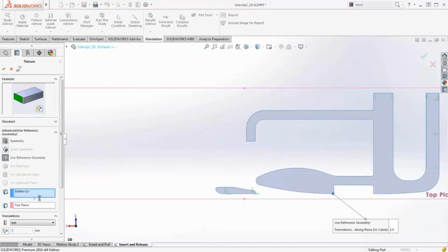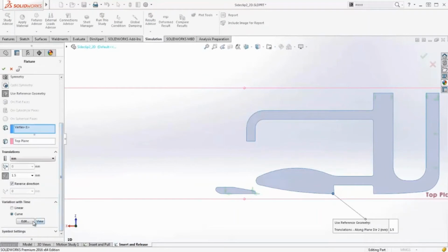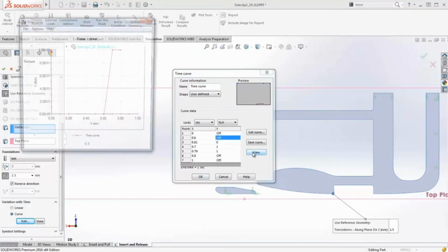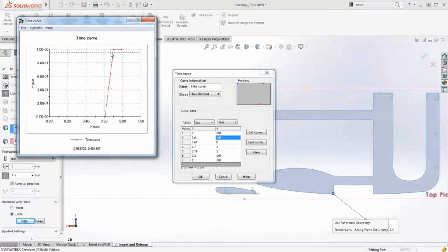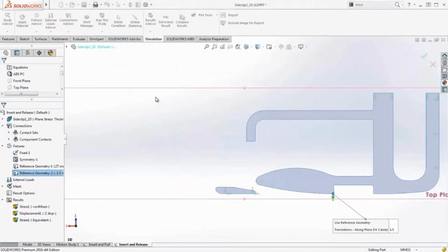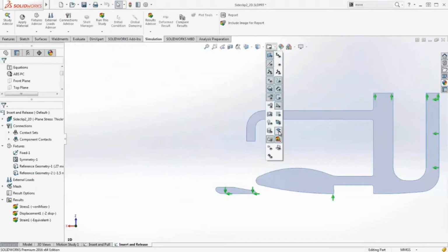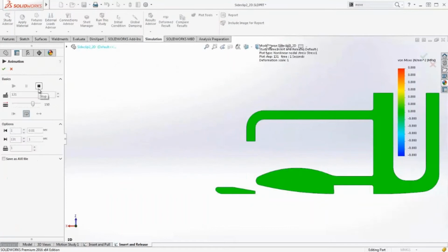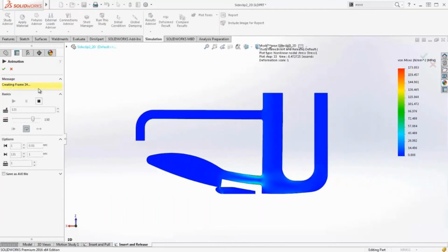The fixture that presses in the side release only needs to be active after the insertion, and until it starts being pulled out, it doesn't need to be active again. This ability to turn the fixture on or off at specific times makes this operation easy. The benefit of sequencing is that the calculated loads are accurate for the entire operation and no artificial stresses are induced. We can then be confident in the resultant performance data and ensure it meets our design needs.